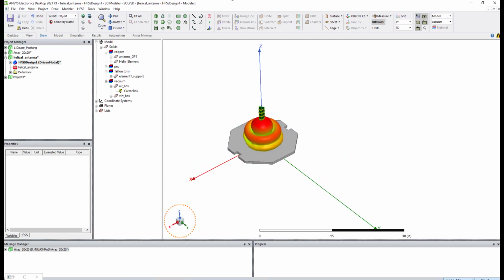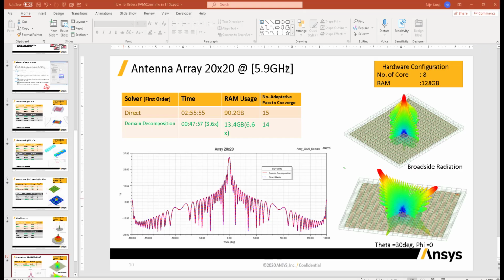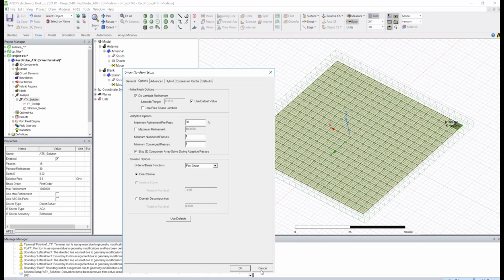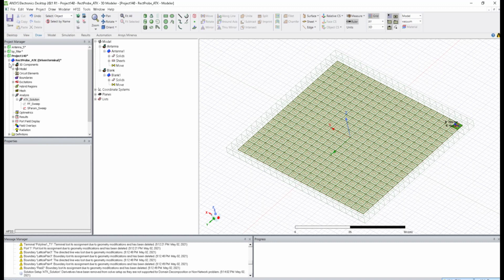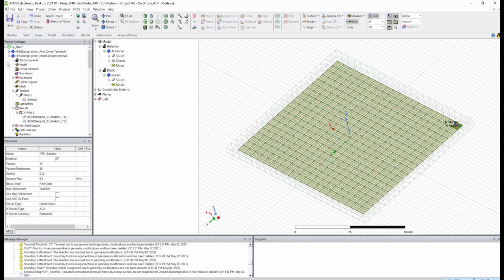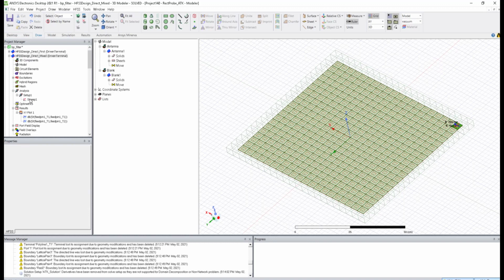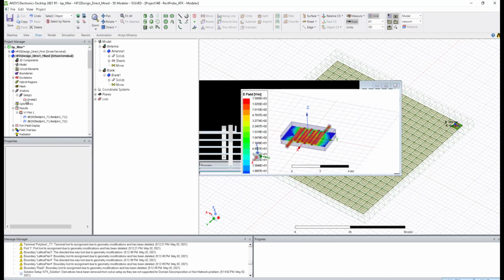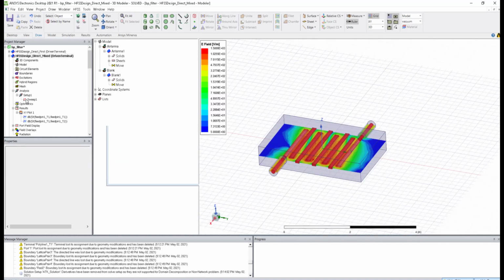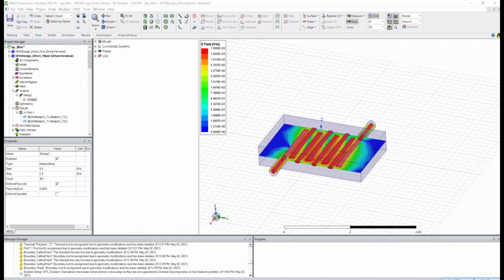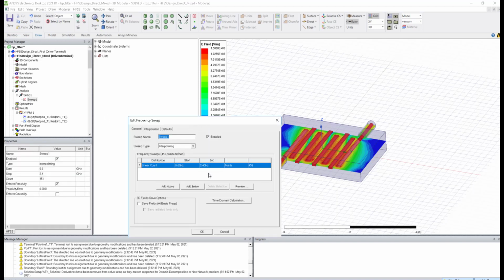I also want to refer one important thing to you on the frequency sweep side. On the frequency sweep, if I go and open one of the filter models, which is a band pass filter or any filter. So I'm taking this particular filter model, and I can use different types of frequency sweep in HFSS. So over here, if you see, I used interpolating sweep, 0.062 to 2.4 gigahertz.